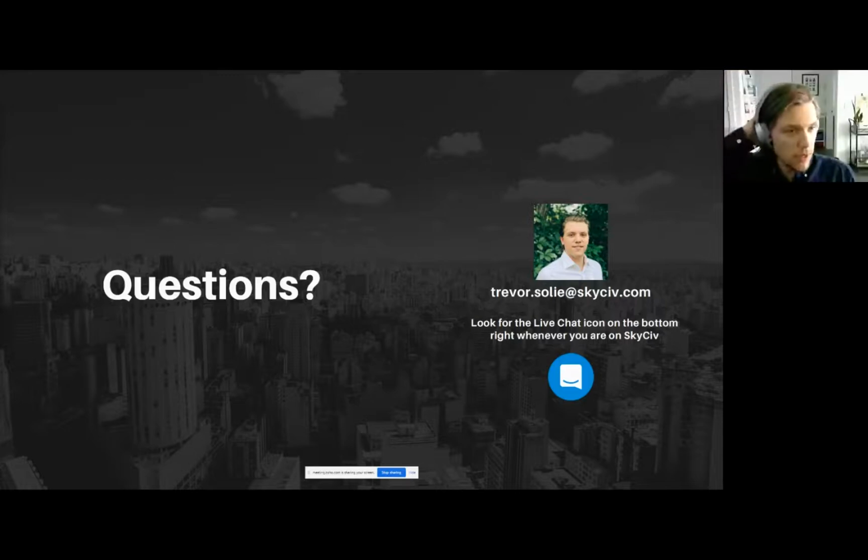Yeah, and just, kind of harkening back to the other question too, if you have your sloped site, or your sloped building, or whatever it is, modeled in Revit or something like that, you could import from that, and you'd have all those bottom node locations for your columns right at the start. And I want to make another comment too about the import-export functionality, which we talked about at the very beginning. If you import or export, specifically when you import from a Revit file or AutoCAD file, it's not like it's all or nothing.